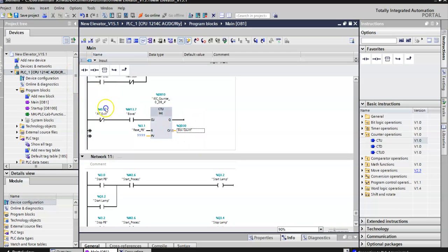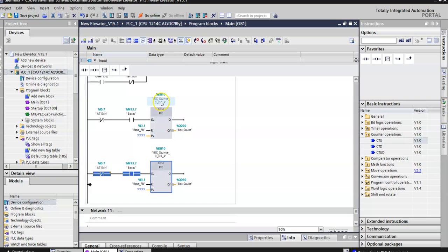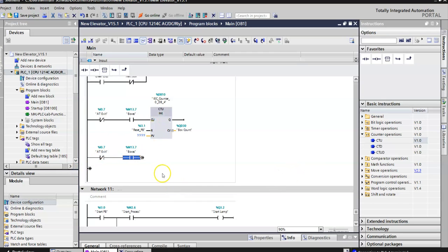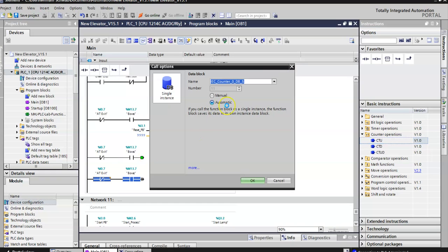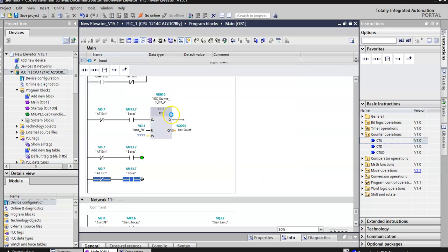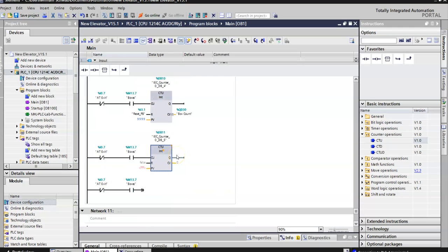If we took this whole circuit and just copied it and pasted it down here, what happens is these are all associated with a database, and so this one's database 4. Because we just copied it, this one's also database 4. They can't both have the same database, so this isn't going to work. So what we have to do, and I'll just delete this guy, we can copy these two, and maybe what I'll do for this is I'll copy these two and put them down here for our third chain. But we need to pull in a new counter value. And what it's going to do is it's going to make this one 5. So the one before it was 4. Now this one's 5. And so they have different databases, so this will work.